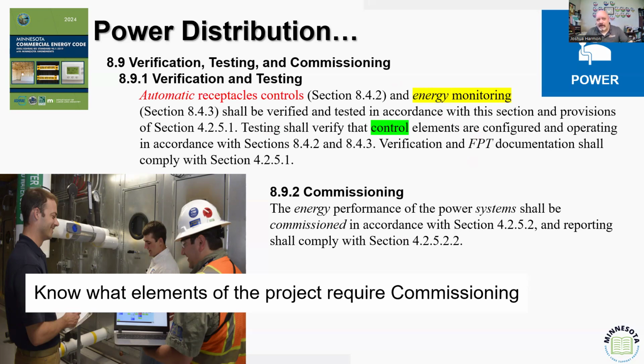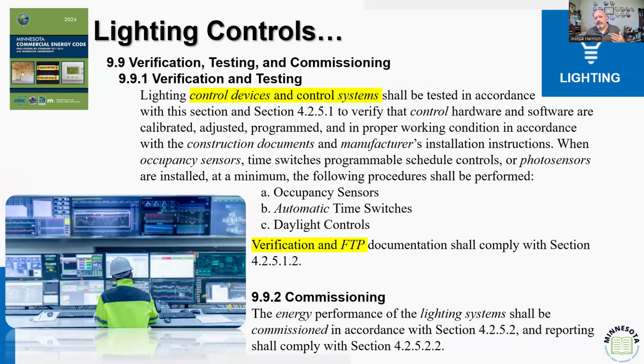Remember, I told you I had a project once where it said, here's all the operations, and the very last thing was to delete all control sequences after final inspection. No, we can't have that, right? We want to make sure that everything, the controls, control devices, systems are all part of that verification that we get at the end, saying how the system works.